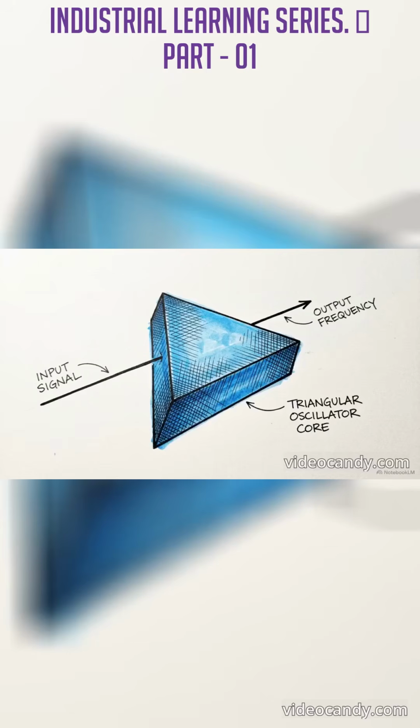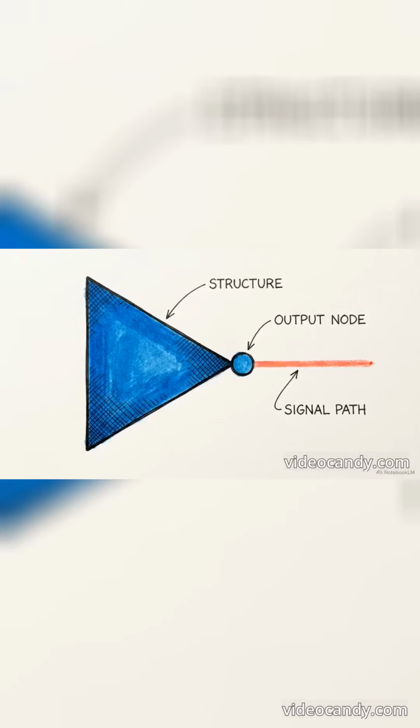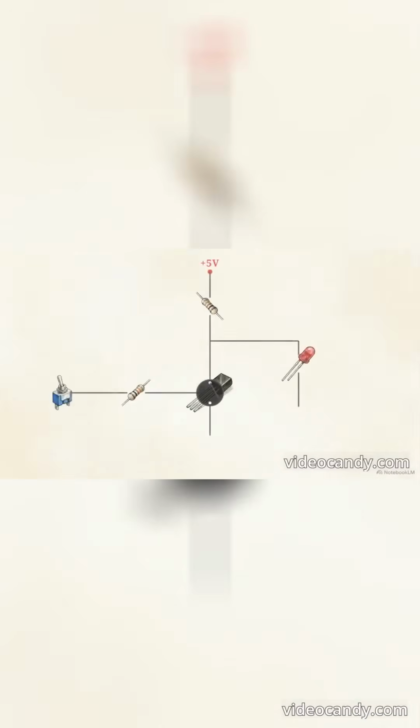We start with the simplest logical operation, the inverter, commonly known as a NOT gate. Its sole function is to flip an incoming signal to its exact opposite state. This schematic shows a NOT gate's internal logic. A 5-volt input turns the internal transistor on, pulling output current to ground, leaving 0 volts. Dropping the input to 0 turns the transistor off, letting 5 volts pass, lighting our LED.